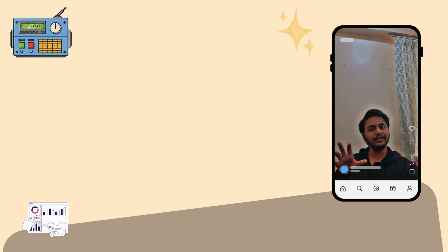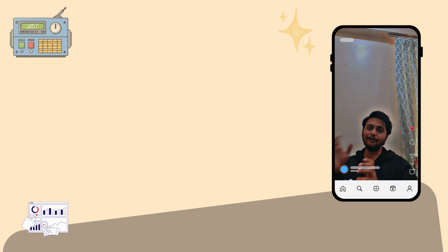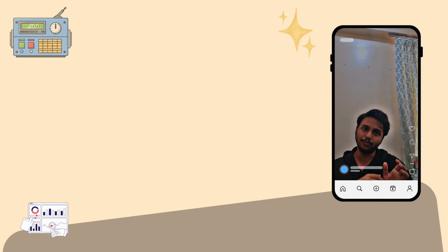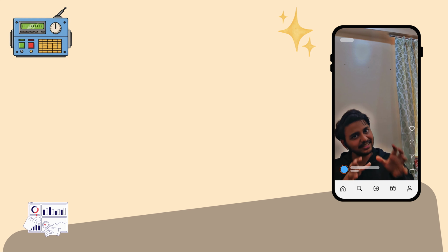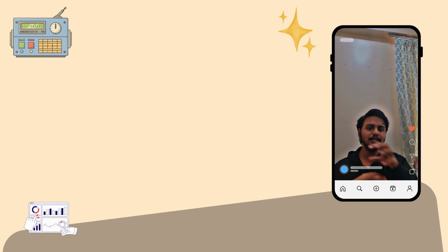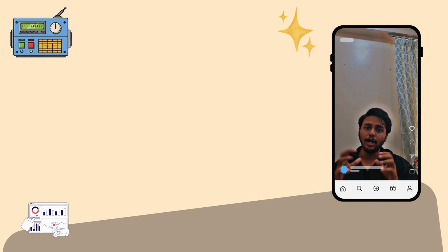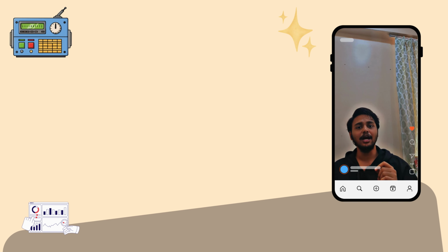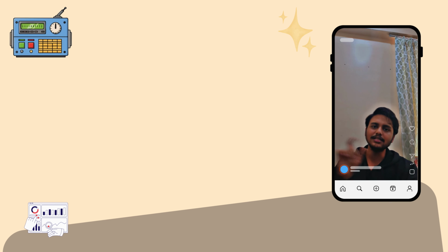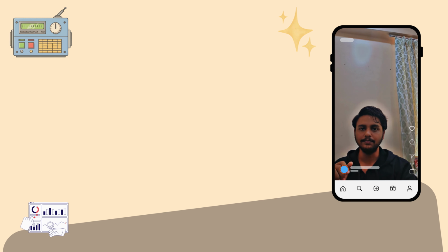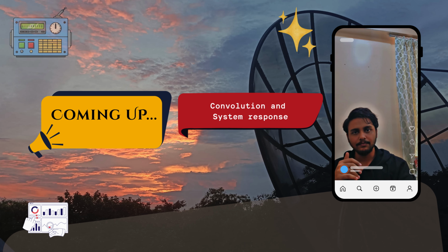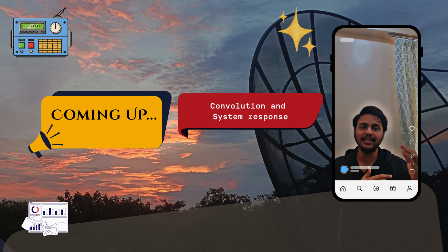If you remember one thing from this video, remember that FIR versus IIR is not about which type of filter is superior. It is about understanding the system requirements and then choosing between them. Do you need linear phase? Do you need guaranteed stability? What is the allowable computational cost for the system? And do you need a fast roll-off? Your answers determine the filter choice that you are going to make. That is what engineering thinking is.